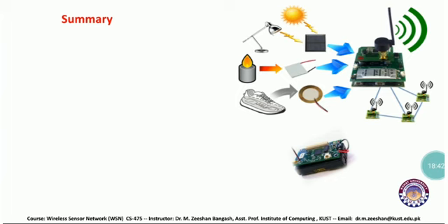Then we discussed the node-centric model, which is basically a programming abstraction that focuses on the development of sensor software on a per node level. We discussed the programming language NesC, which is an extension of the C language and provides a set of language constructs to implement code for distributed embedded systems like motes.